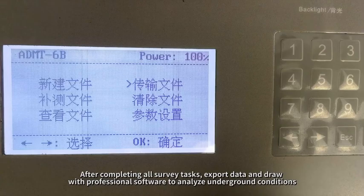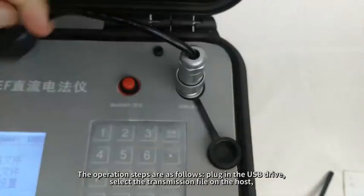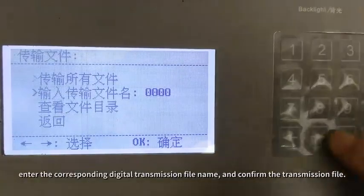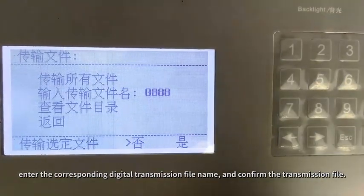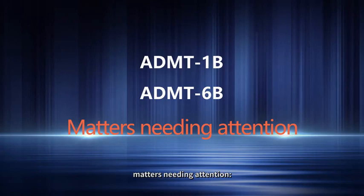After completing all survey tasks, export data and draw with professional software to analyze underground conditions. The operation steps are as follows. Plug in the USB drive, select the transmission file on the host, enter the corresponding digital transmission file name, and confirm the transmission file.